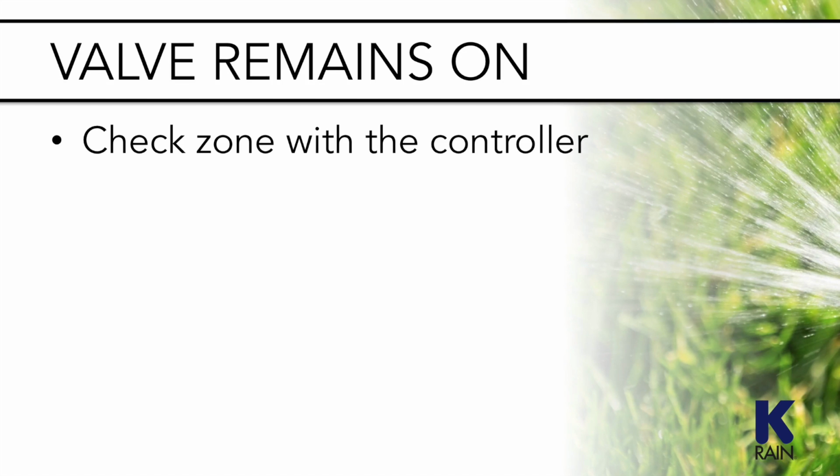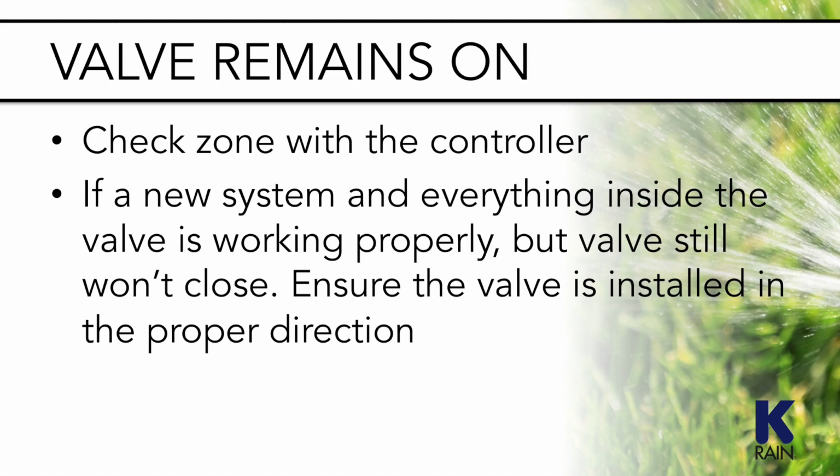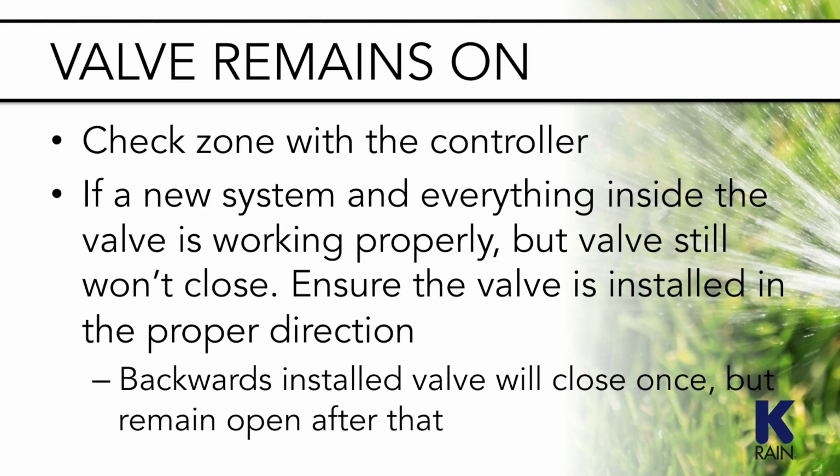One small reminder, if this is a new system and everything inside the valve is working properly, but the valve still won't close, make sure that the valve is installed in the proper direction. A valve installed backwards will close once, but afterwards remain open.